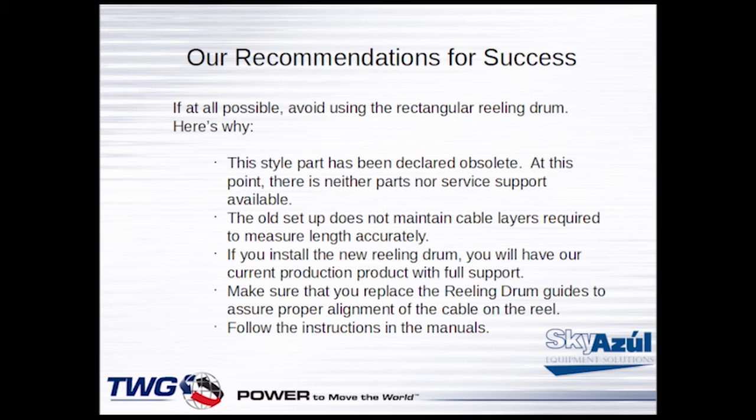If you install the new reeling drum, you're going to have our current production product with full support. You're going to have an easier setup, easier to maintain, the whole nine yards. Make sure that you replace the reeling drum guides, because nowadays we don't let the cable just go wherever it wants to. We have a longer guide that sticks out there and lines it up and lets it level wind across the reeling drum. So there's a cable guide kit that comes with it, and you need to follow the instructions in the manual.